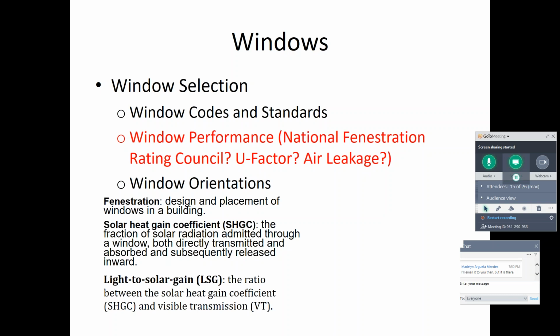If you're looking at online, it would usually say click here for dimensions and any more information, which is where you should find, was it approved by the National Fenestration Council? What is the U factor, and what is the air leakage? And actually we want it to be low air leakage, not high air leakage, because it's thinking about how we're preventing it from happening.